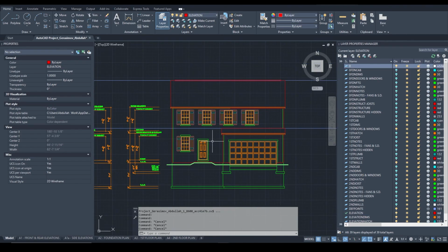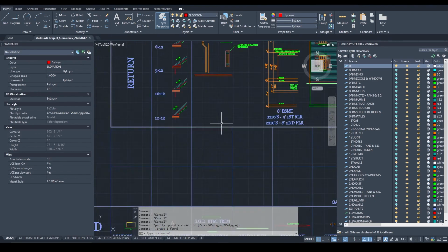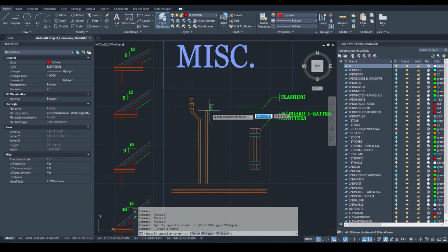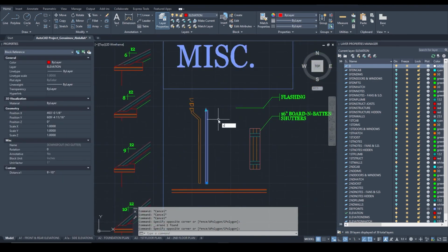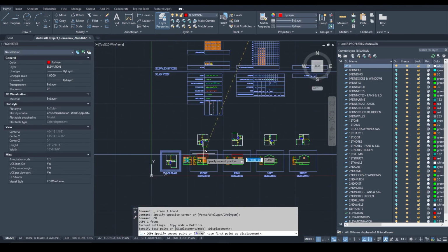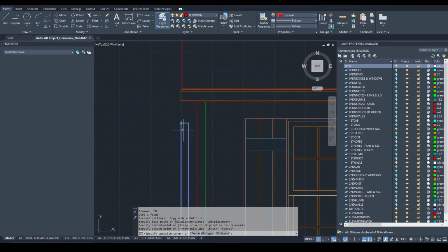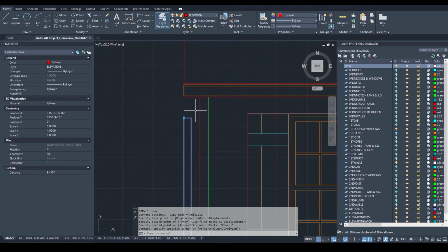One of the last things that we're going to do is draw downspouts, but only on the front elevation. Let's go ahead and remove the reference line that I've shown. Let's go to the blocks area, and under miscellaneous you'll see a straight rectangle. Let's copy it to our front elevation only. We're not going to focus on the rest of the elevations in terms of downspouts for now.